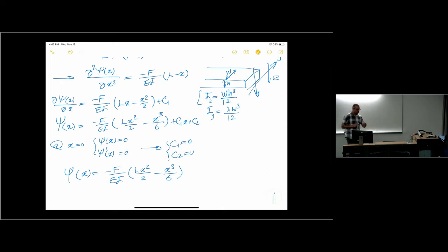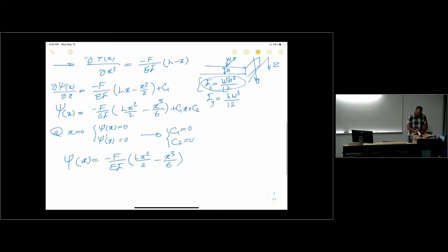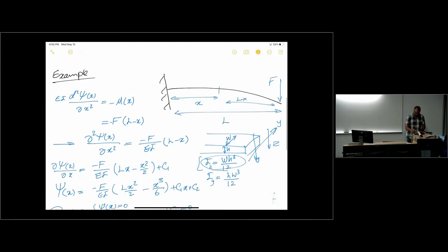Notice that we didn't really have to calculate I, but for a beam of rectangular cross-section, you go and use, for example, this I if it is bending downwards, or the other one if it is bending in plane. Okay? What I can find out now is that for this force F at x equal L, I want to calculate how much deflection I get.